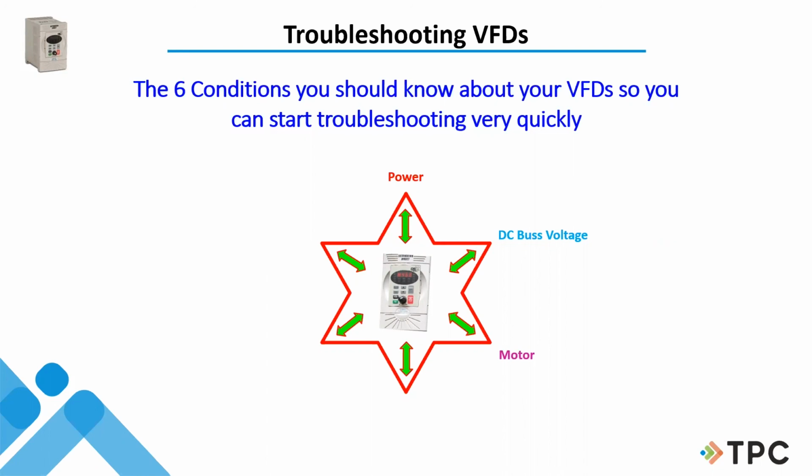I need to have an SOP, a standard operating procedure, for checking motors. I make sure I know how to check it with an ohm meter. I know how to check it with a megohm meter, so that I know if I have problems with insulation, or problems in between phases and all that kind of thing. So what is your SOP for checking a motor?